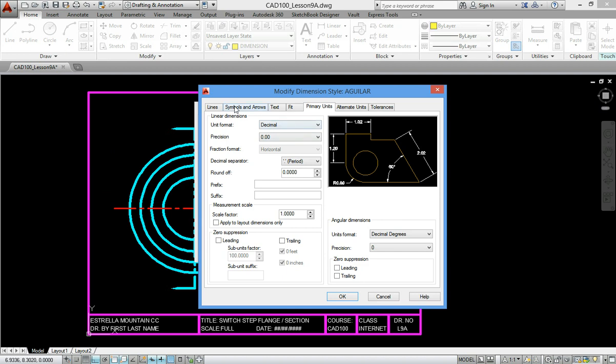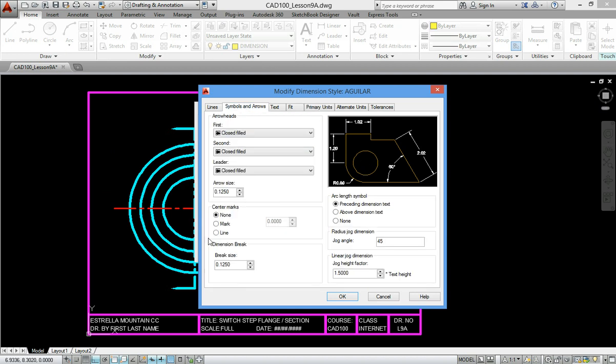And before we leave here, I want to talk to you about center lines. The default is mark. If you want to automatically put center lines in, you can do that this way. However, they will not be red center lines, and sometimes the pattern will not repeat, but you will get a nice center point. Drafters are not required to have that perfectly centered, but if your boss asks you to do so, use this option. I use the none command option.